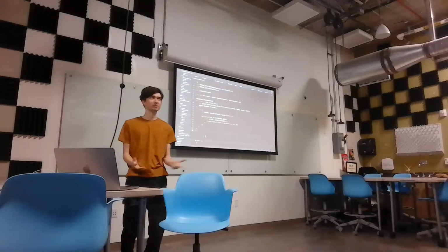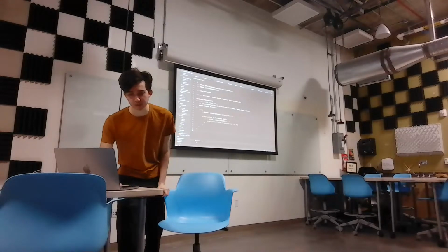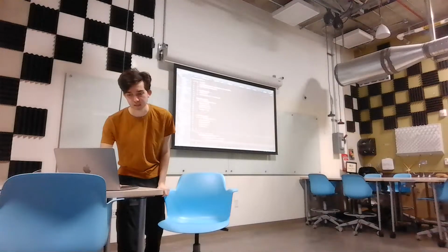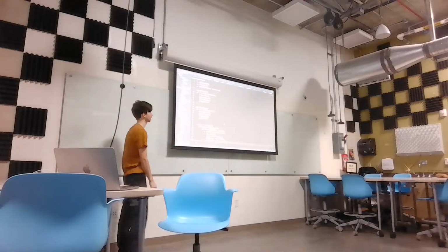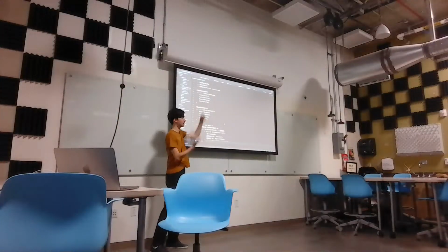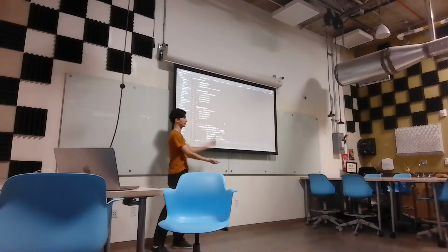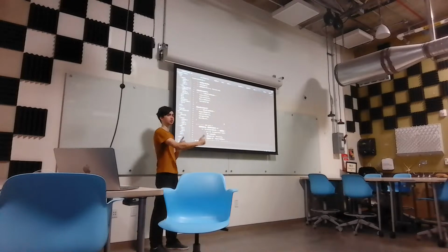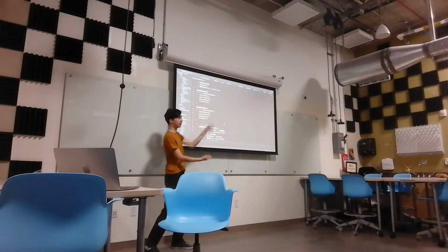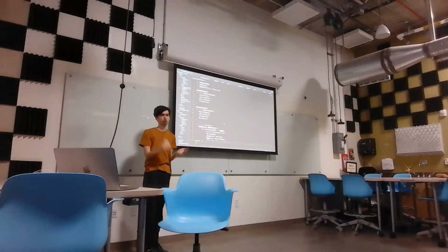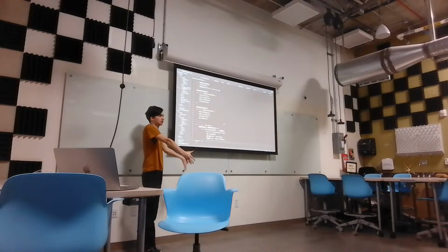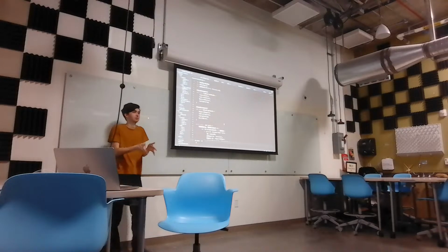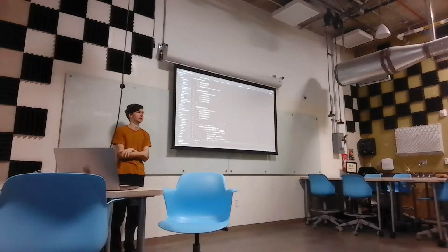And I made another procedural macro that just generates bundles for me. Here's what they look like. The first bundle are commands from the headlight. The headlight can send us a status. It can send us a control saying here's what the current control settings are. It can send us a monitor command, which has temperature, duty cycle, measured currents, stuff like that. And it can send us what its config is. The config is stored in Flash, data that persists, the configuration of the headlight.